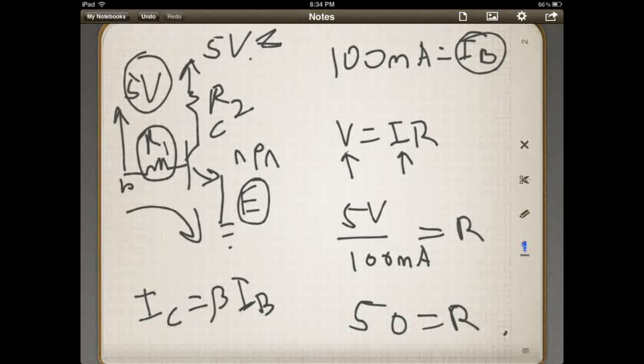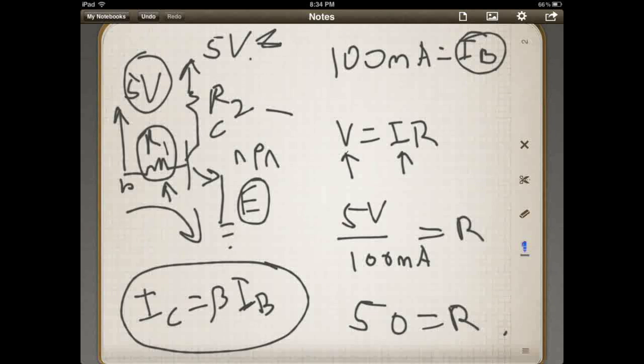If it be an N channel that you're sinking through to ground, then an NPN. But that's the main equation you want to use, and you can vary your base current to get different collector currents. That's how you do that, and they're linked through that DC current gain. That's why it's called DC current gain, because essentially whatever you put through, it gains.